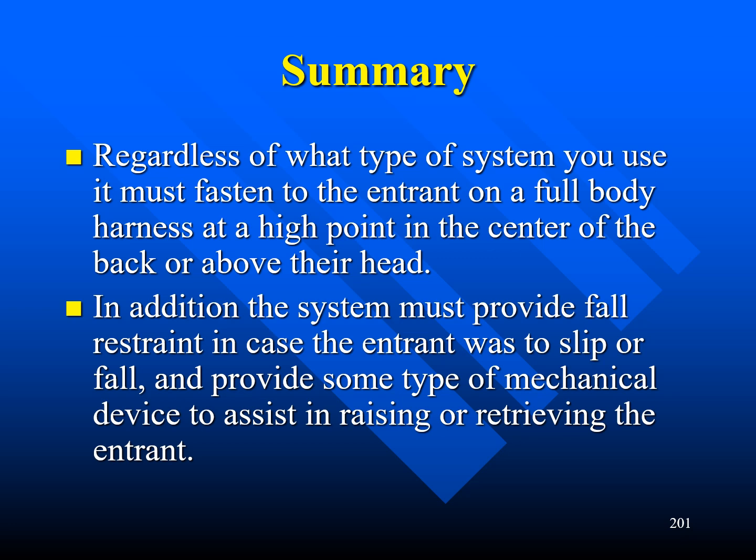Regardless of what type of system you use, it must fasten to the entrant on a full body harness at a high point in the center of the back or above their head. In addition, the system must provide fall restraint in case the entrant was to slip or fall, and provide some type of mechanical device to assist in raising or retrieving the entrant.